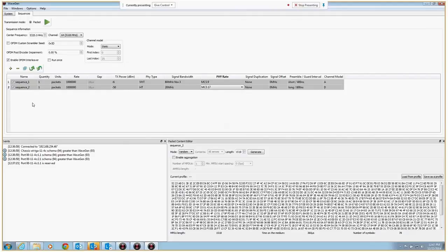That can be done. No other tool in the marketplace can change the channel model on a per packet basis and map them to individual clients. So we could build a sequence here of 500 individual steps, because the architecture of the card has 500 unique client contexts. Any sequence that you can imagine that would be important to you, you can create a packet at a time, some number of packets at a time, change power level from one step to the next, change channel model, change the payload type from one to the next.